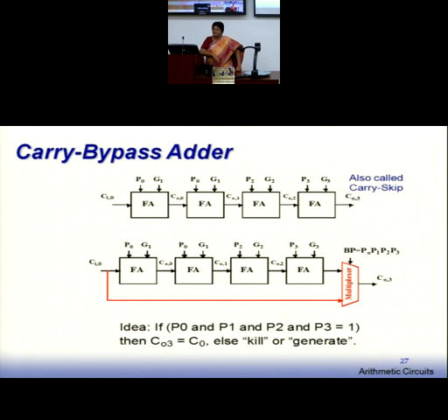You know the structure carry skip adder? It is the RCA which is modified, or it is also called carry bypass. What is the innovation in that? What is the thinking in that? What are you bypassing here? What are you skipping here?